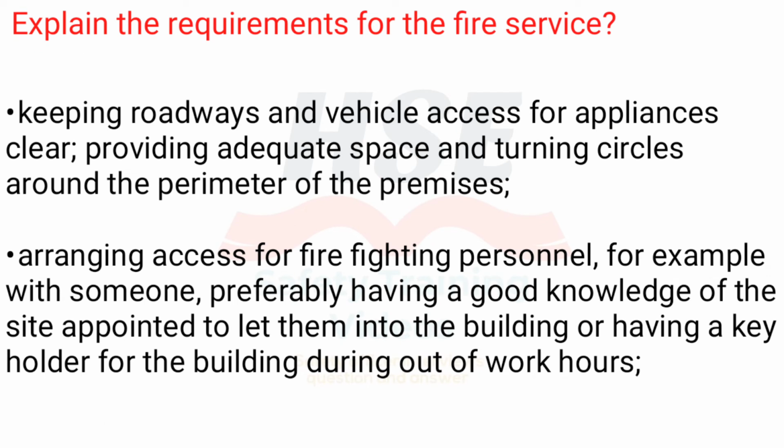Explain the requirements for the fire service. Keeping roadways and vehicle access for appliances clear, providing adequate space and turning circles around the perimeter of the premises. Arranging access for firefighting personnel, for example with someone, preferably having a good knowledge of the site, appointed to let them into the building, or having a key holder for the building during out-of-work hours.